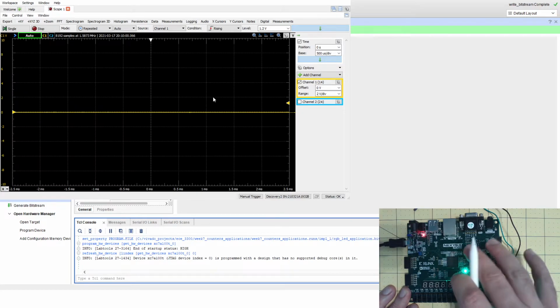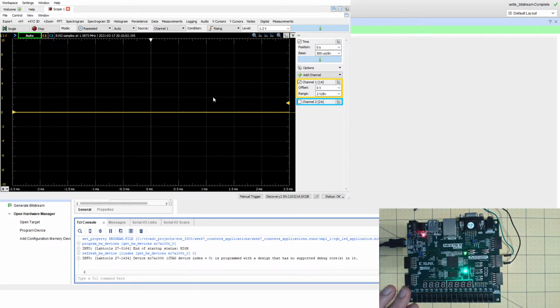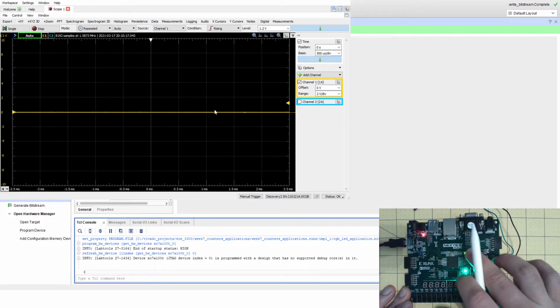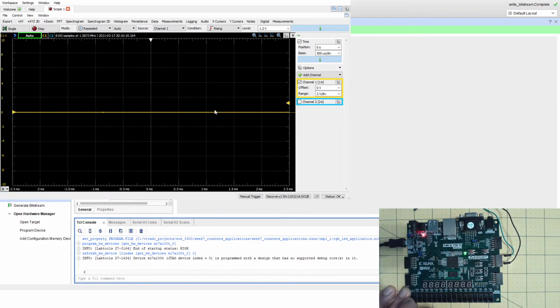Okay, what I did is that when I did reset, it put 000 in all the colors, and now I just wrote whatever I put in here, which is switch number 7, which is pretty high. It's like 128 or so. So the duty cycle is high. Of course, you can't see it on the diagram in here because I'm only outputting the red. So the last one is here. I can put the 2, and I can definitely write that to the blue.